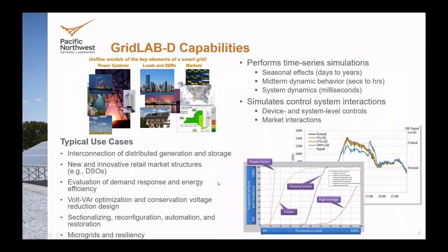So here's just some more high-level points on it. The big thing with GridLABD that's not as unique anymore, but really was when it was first conceived, is doing time series analysis. A lot of your traditional distribution system evaluation tools at the time only did snapshots. They would do something like the peak load day, or maybe the hottest day of the year. They wouldn't really capture any of the time evolution of the system, and that became very important when we started looking into things like demand response and using load as a resource, which I'll get into in a little bit.